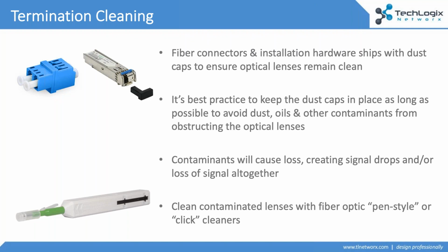And if you need to clean the connectors, invest in a pen style or click style cleaner, right? These are small, inexpensive little cleaners. You literally just pop it into your connector, click it. It cleans that connector of any debris or oil or whatever it may be. Great little tool to have in the toolbox, but make sure those connections are clean.